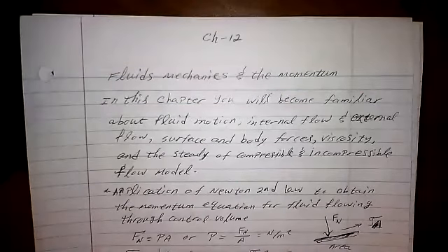The special part of the Bernoulli equation says that if air is assumed to be incompressible flow, because the density doesn't change. Incompressible means density doesn't change. Compressibility means the density at inlet and outlet will change, because we're compressing air in a piston and cylinder, for example. Okay, and Bernoulli said if the flow is incompressible, even if you're dealing with air, under certain conditions, you cannot just say that air is incompressible. Air is a compressible substance, but we have a case. If that case is satisfied, then we say yes, we can assume that air is an ideal gas, it's incompressible.